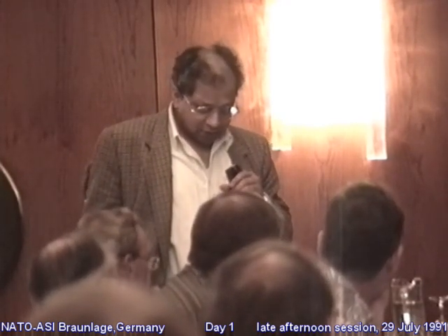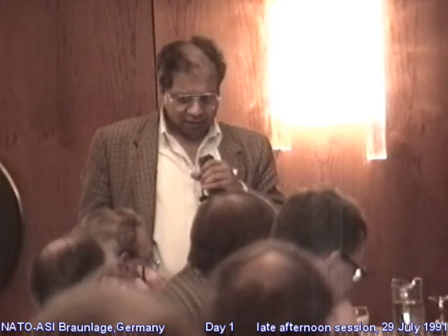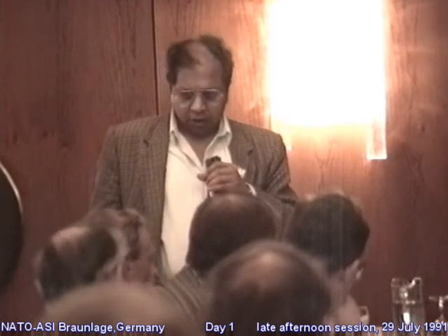I think this is an extremely important question, and in connection to what Hubert Pollock said, and also what Briscoe said, we did specifically a lot of experiments. In these experiments, we tried to use flat-faced cylinders instead of spherical surfaces, because spherical surfaces tend to be very difficult to control, because the geometry and the loading make the contact area change.